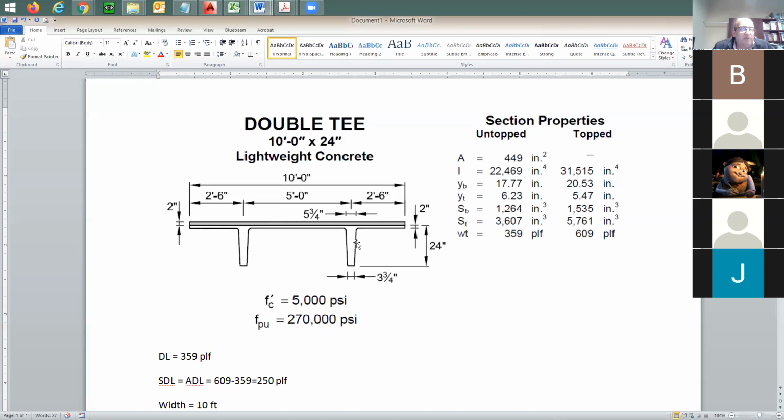You applied it already to the double T, and the double T has taken this already, and the stress is locked in. You have all of these compressive stresses already in the double T without the topping. When you put the topping on now, it is not going to take any stresses from the compression, from the pre-stressing. Does it make sense?